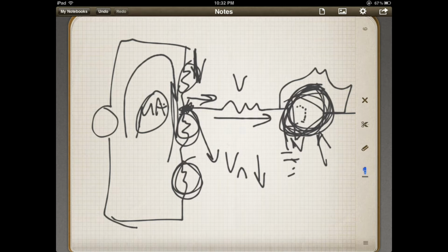What's giga minus 9? So that'd be pico amps. It's robbing pico amps. No, that'd be nanoamps. Sorry, my bad. I can't do math right now. That'll be nanoamps. So if you've got like a microamp circuit or whatever, you see what I mean. That's what you got to look for, and that's what is important when choosing your op amps, that you make sure you choose one that has the correct impedance, correct leakage stuff, depending on what you are doing.